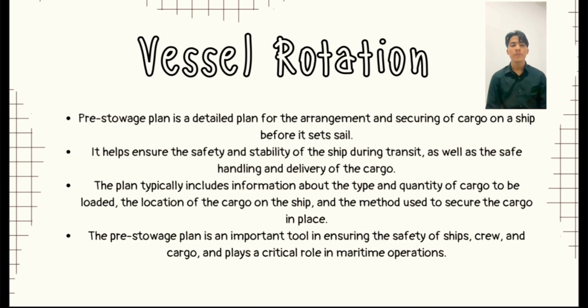In conclusion, a cargo storage plan is a crucial document for the timely and secure delivery of cargo by ship. According to the IMDG code, it must take into account the pre-stowage plan, vessel rotation, weight distribution, and suitability of the cargo, and safety should make certain that the cargo is loaded and secured in the most effective way. That's all for me.